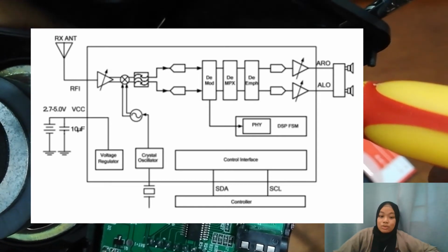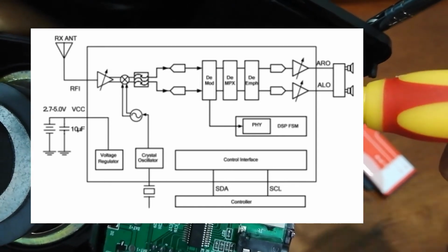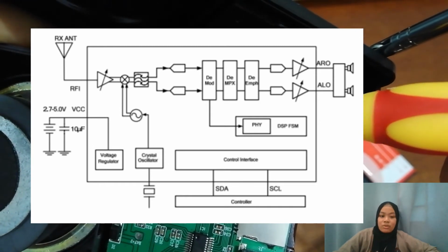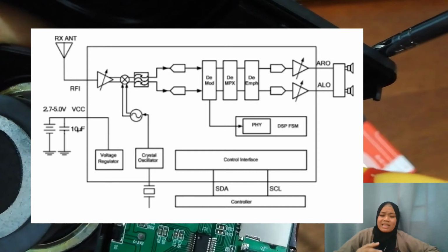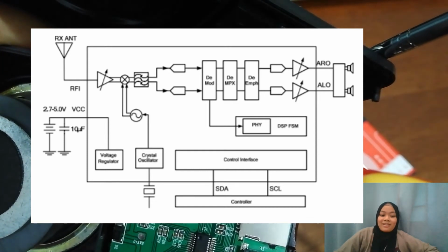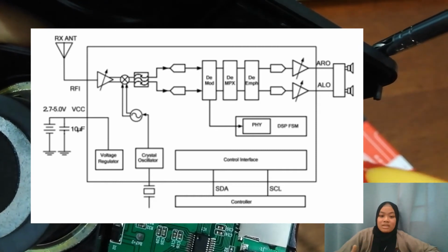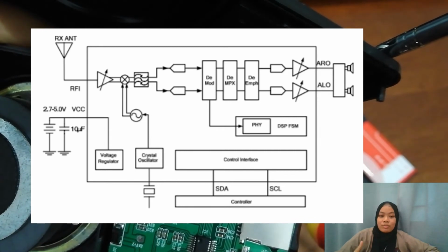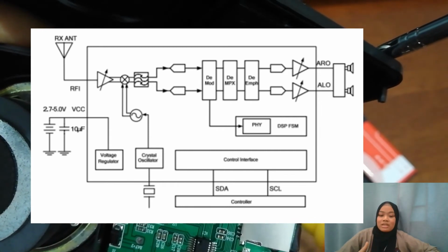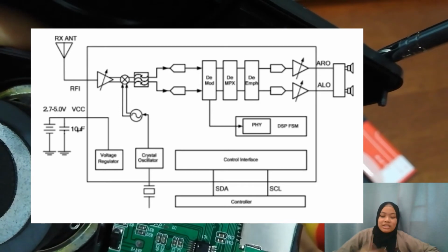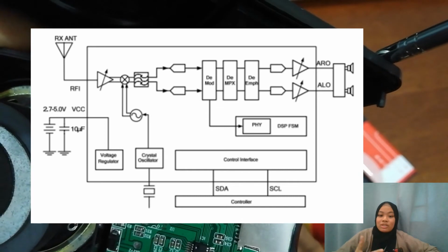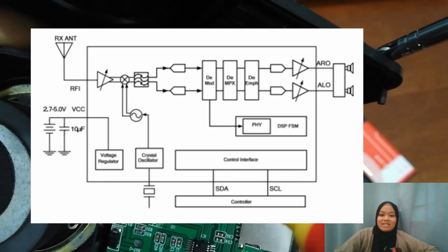The automatic gain control, AGC, is also performed simultaneously to optimize the signal to noise ratio as well as linearity and interference rejection. The filtered signal is digitized for further processing with a digital FM demodulator and MPX decoder. Audio processing is then performed based on received signal quality and channel condition. Two high-quality audio DACs are integrated on this chip to drive the audio output.